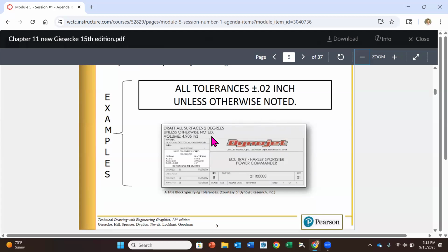So a title block is always going to include company information and any disclaimers, if you would, of ownership. You're also going to see here these tolerances, these standard tolerances. So you always look to the title block. Once a company identifies those, they can never be changed. Those are part of the title block. So if on a drawing, you're like, I don't want to use the title block tolerances, I'm going to change those in the title block because all of my two-place decimals are going to be something else. You can't do that, all right?